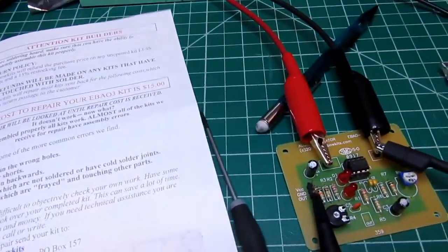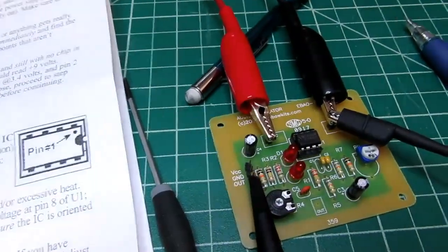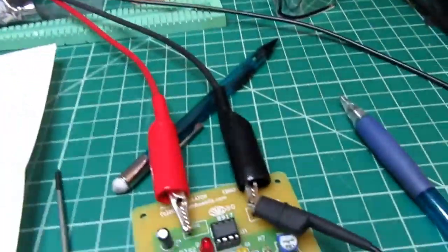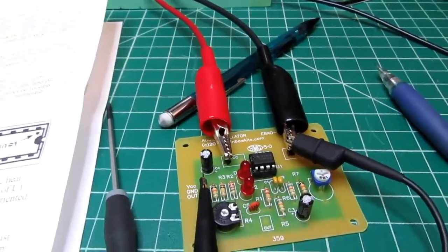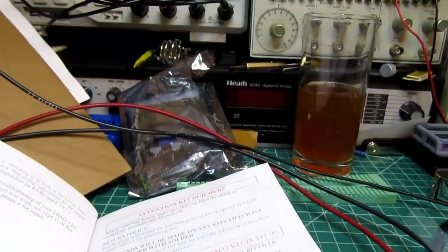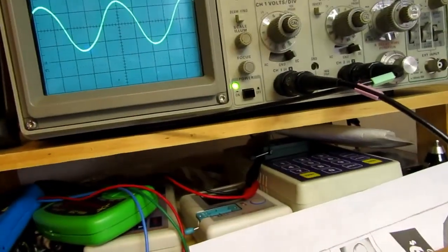Well, I turned the page in the instructions. It tells you how to check for optimum results if you don't have an oscilloscope, just based on DC voltages. And you know, I've optimized the waveform as much as I can, but then you turn the page and you think it'll tell you something about how to adjust the other pot, and all it says is have it in the middle of its rotation, which is kind of odd. And this is a 10K pot instead of the 5K it's supposed to be. So maybe it should be more like this.